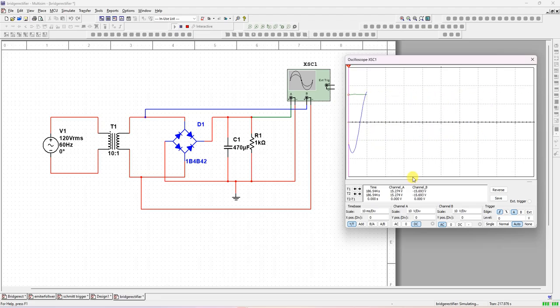So what is the aim of the experiment? Without the capacitor filter, we got output with more ripple content. The output is going up and down, up and down. That is the ripple, the unwanted AC present in the DC. So we use a capacitor. Now that unwanted AC is removed, and the output is coming almost as a straight line like a DC waveform.